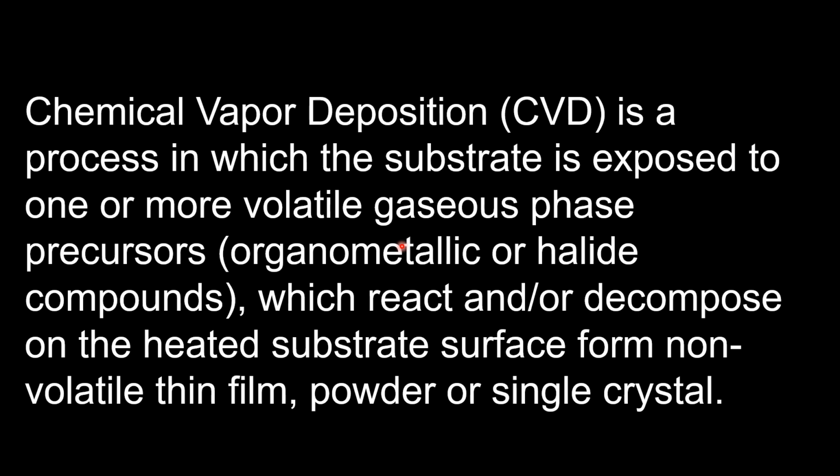So basically, in the chemical vapor deposition process, initially the precursor material, which is basically a reactant material, is introduced inside the reaction chamber, and when the precursor material reaches the surface of the substrate in the reaction chamber, due to heat the precursor material gets decomposed. Basically they get separated into two or more fragments,